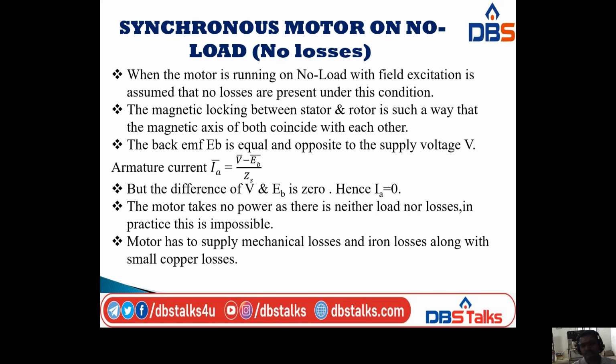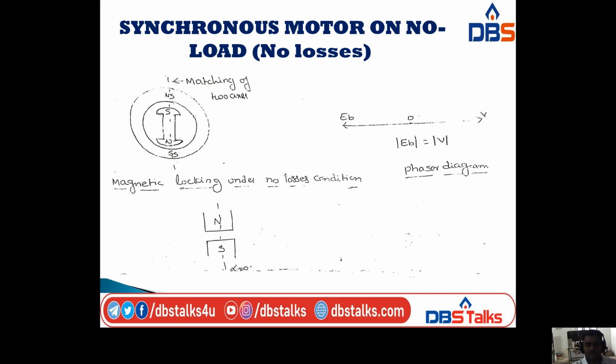In practice this is impossible, because the motor has to supply mechanical losses, since it is a rotating device, and iron losses along with small copper losses. This will happen in practice, which is why I say this is impossible in a practical manner.